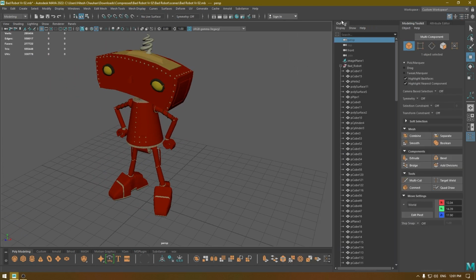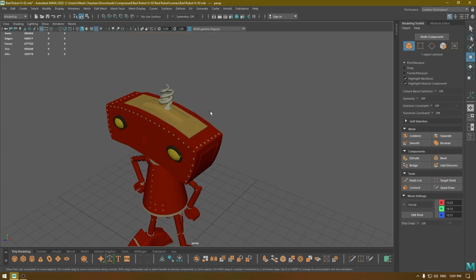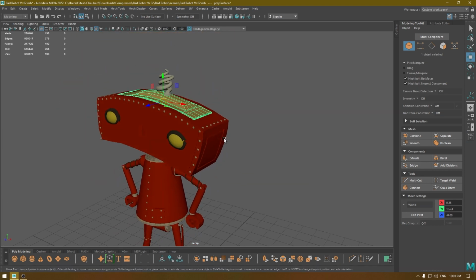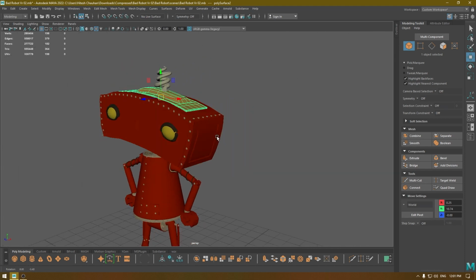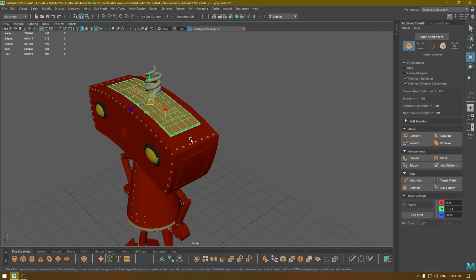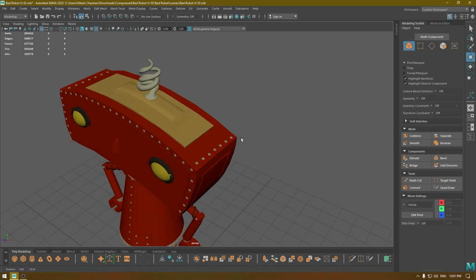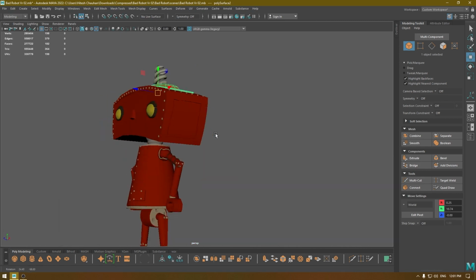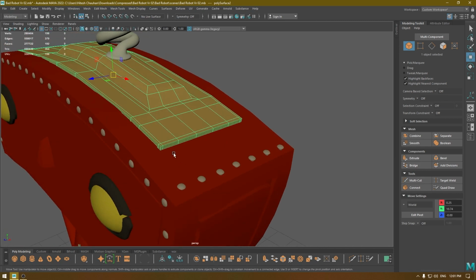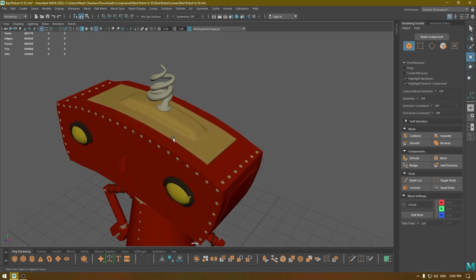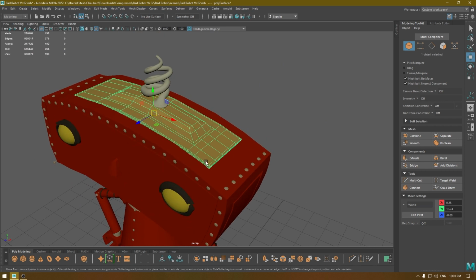Now let's unwrap it. So we are going to create this high poly model. This is going to be a production model, so we don't have any constraint or budget issue about polygons. So all of these are still in the blockouts with supporting edges. So if we smooth it, it's going to be converted to a high poly mesh. So we're going to unwrap this mesh first, then we're going to apply the smooth modifier.